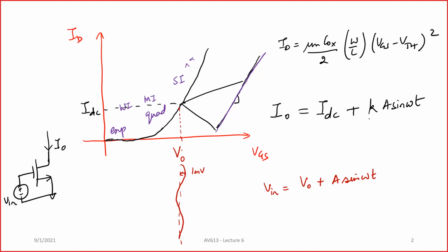And now this factor, which relates this voltage quantity to the current, is called the transconductance. Let's call it GM. This is what is called the transconductance. All right. Now, what is transconductance? So basically, let's take an example so that we understand it well, right? So let's call this your V in, and let's call this your I out.